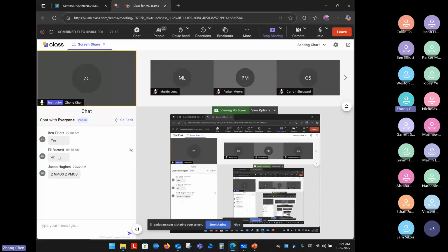Yeah, PMOS, you have four. The correct answer is four PMOS and four NMOS, all right? Then the next question is whether the PMOS is in parallel or in series. In parallel, all right? That's correct.